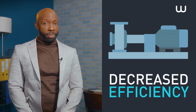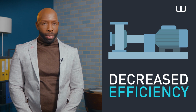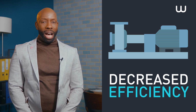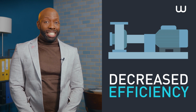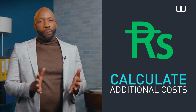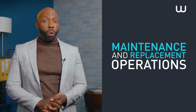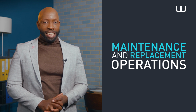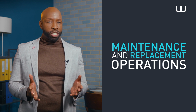The purpose of an energy audit is to help the operator to reduce the electricity consumption of pumps. It evaluates the specific energy and efficiency of each pump. This then allows us to identify pumps whose efficiency has decreased with time and to calculate additional costs that may be caused by this. The operator can then identify which pumps need to undergo maintenance or be replaced. This leads to significant savings to be made in a water utility's operating costs.